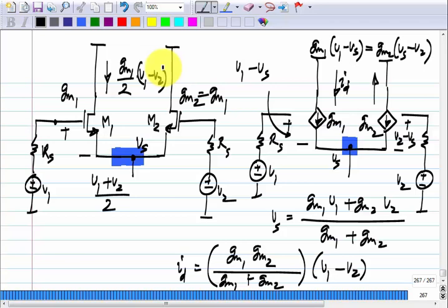Yeah. So, there are some practical problems that will come up. Okay. So, now we have chosen a model in which we have ignored the output conductance and all these things. So, the best result will be obtained when we have identical transistors, okay, which are biased identically. Any other questions? Keeping? There is, we will see. I mean, after we introduce the bias, there may be some use. Most of the times it is not used that way, but you could think of some things. Any other questions?